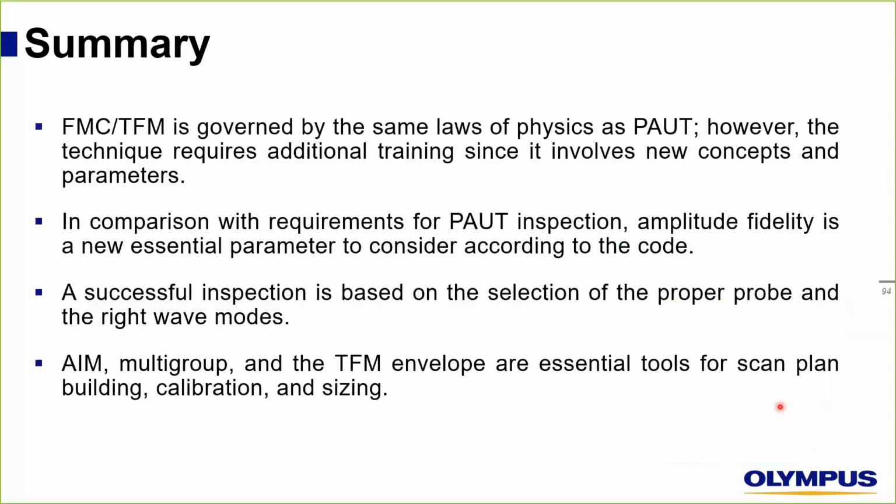Now, let's have a summary, and let's have the conclusion of this webinar. So, FMC TFM is governed by the same laws of physics as phased array. However, the technique requires additional training since it involves new concepts and new parameters. In comparison with requirements for phased array inspection, amplitude fidelity is a new essential parameter to consider according to the code. A successful inspection is based on the selection of the proper probe and the right wave modes.